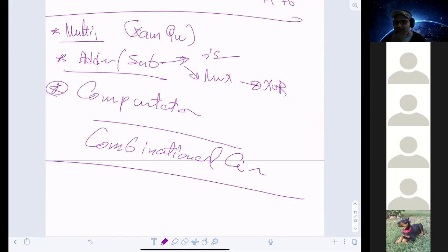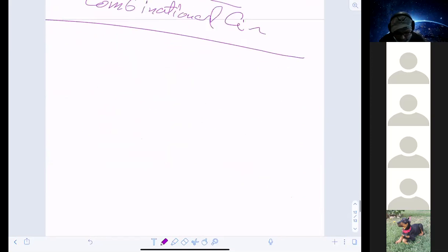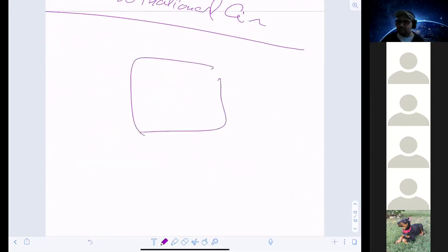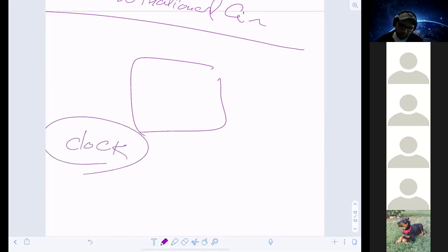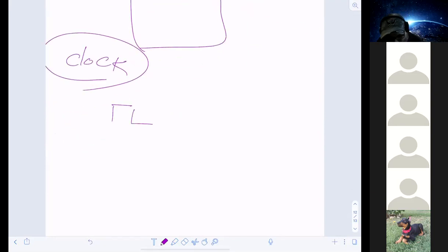What's the difference between combinational and sequential? Huge difference. In combinational, everything is gates. In sequential, there are elements that act as gates, yes, but they actually run with time, on something called a clock. We're going to describe what the clock is. The clock is basically a train of pulses with a periodic time called T. This thing is repeated and the distance between pulses is equal.